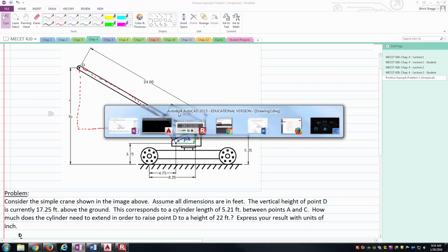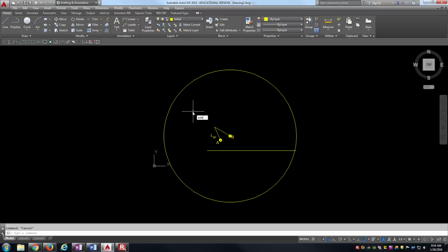So what I can do is I can just use extend, and so I can just type in the first part of extend there. You can see it picking up the tool command inside of AutoCAD. I'll just accept that. I'll select the boundary that I want to extend the line to, hit spacebar to accept that entry, and then I'll select the line segment.